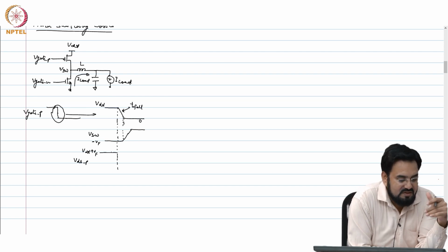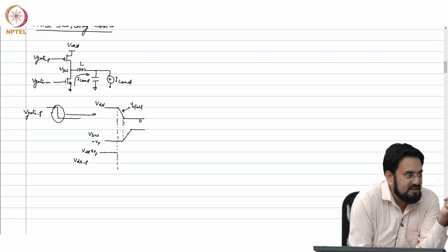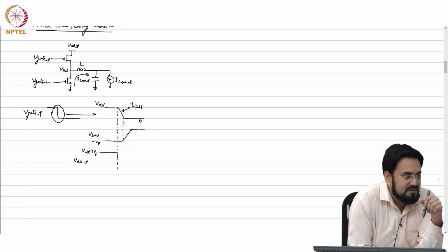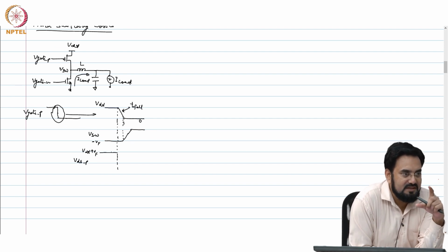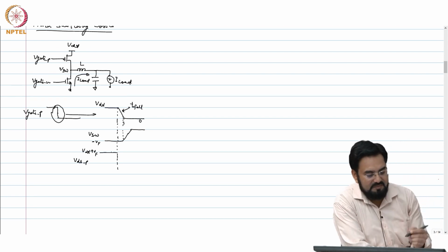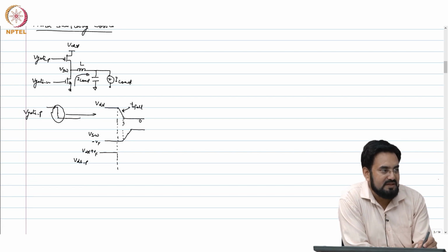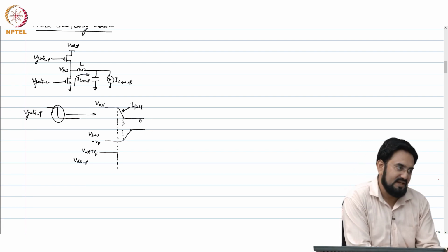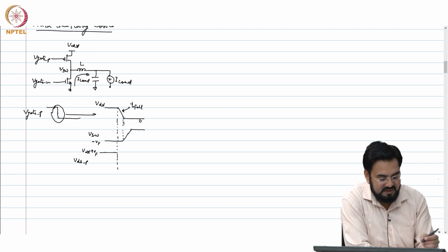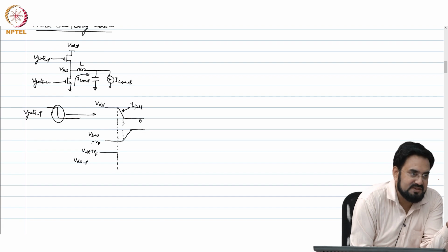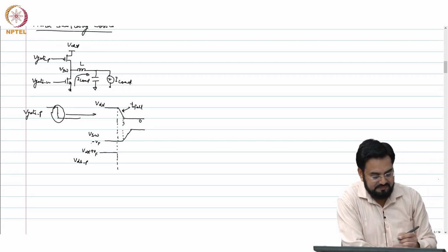When this is on, VDS will be VF plus the IR drop, but since before you turn on the PFET your body diode is already conducting, that is why it becomes VDD plus VF. Usually they consider this as 0 volt, which in reality is not true, and it is not a small amount, like 0.7 or 0.6 volt. So, you have to consider that.